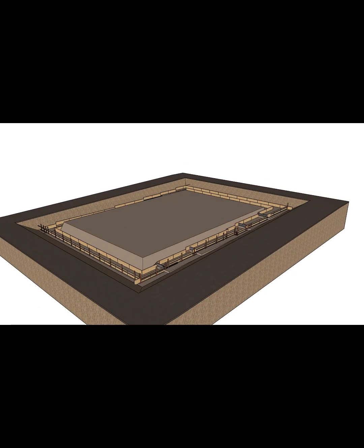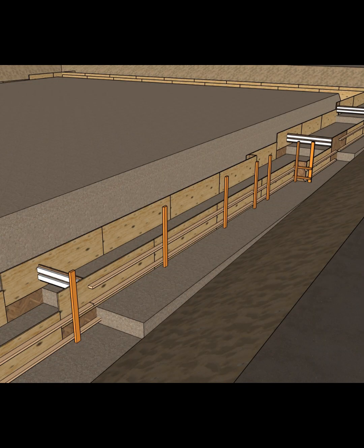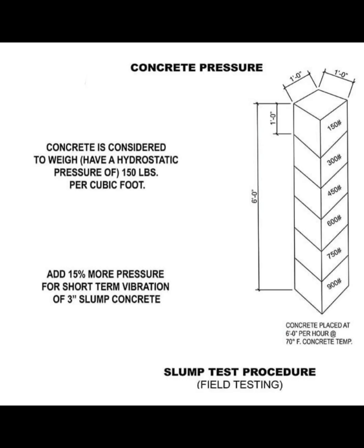Let's start building the footings. Standard construction means and methods with 2-foot wide ripped 3/4 inch MDO form plywood. Use 2x4 for whalers and strong backs. Use nails sparingly to make it easy to strip. Remember the forms are only holding about 300 pounds per square foot pressure during the placement of the concrete. You can calculate this easily. For every foot up the form, add 150 pounds. So a 2-foot tall form has 300 pounds of pressure.